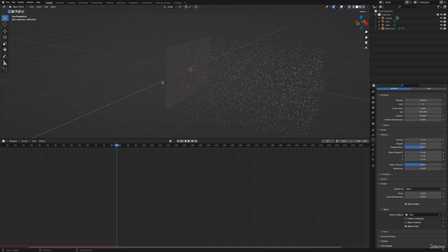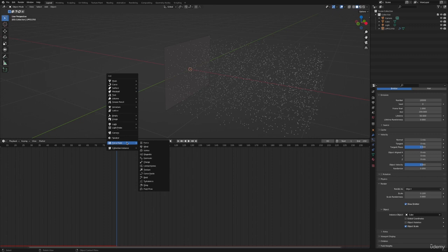However, we can get creative again here, for example, with force fields. In general, everything that we did here with the physics so far can also be supplemented with force fields. Doesn't matter which simulations we have, whether it's rigid body simulation, cloth simulation, particle simulation, fluid simulation, or soft body simulation, we can always work with the force fields to make things more interesting.